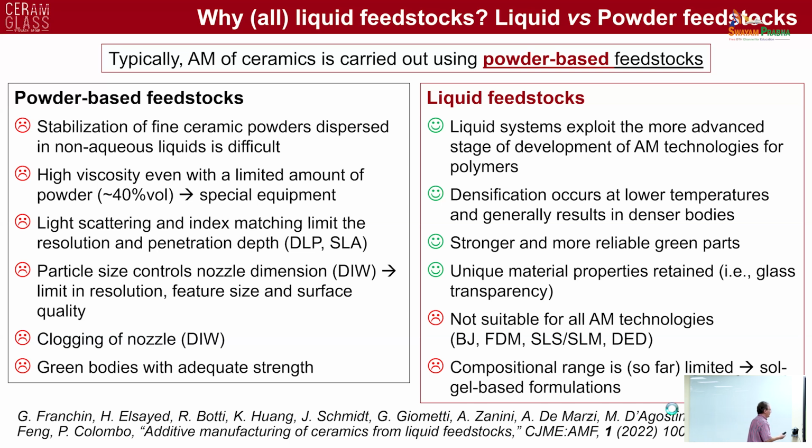But especially for polymer-derived ceramics, you have limitations in terms of the compositions that you can obtain. If you don't want silicon, then it's very difficult to use preceramic polymers, because there is only a polymer for boron nitride that can be used, which is borazine. So if you want to make titanium carbide, you cannot make it from a polymer, because there is no titanium-based polymeric material available, or I don't even know if you could make one.